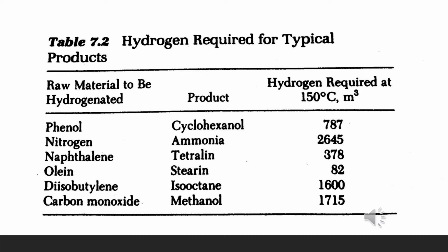Liquid hydrogen is the most profitable, is produced by only three companies, and is shipped by tank car, truck, or barge. Gaseous hydrogen is made by many companies and is shipped in tube trailers holding about 4,300 cubic meter.